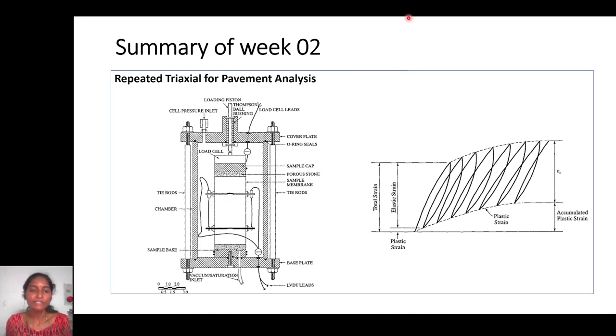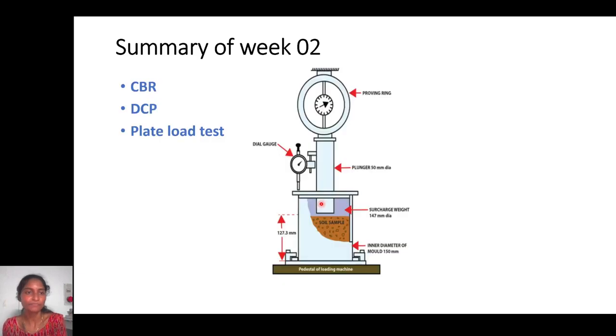The advantage of that is, by applying the repeated loads, we can determine what is the plastic strain, what is the recoverable strain, so that we can calculate the resilient modulus. Using this resilient modulus, we can actually do pavement analysis and design, because this resilient modulus will be input for the subgrade modulus.